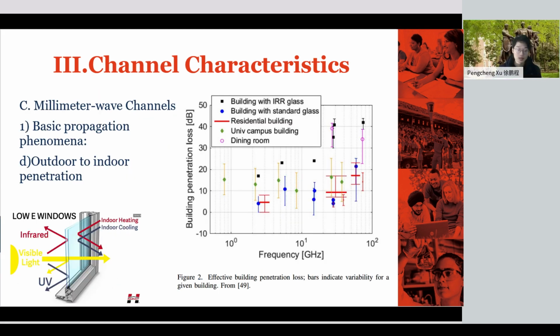Outdoor to indoor penetration is very important because a large number of cellular users are located indoors, and coverage by outdoor base stations will be a major goal for 5G systems. However, the penetration through windows and houses is more attenuated at higher frequencies. The actual values of attenuation strongly depend on the material. While wood and drywall have less than 10 dB attenuation, the steel concrete of brick buildings in combination with energy-saving windows can impose 20 to 40 dB loss.